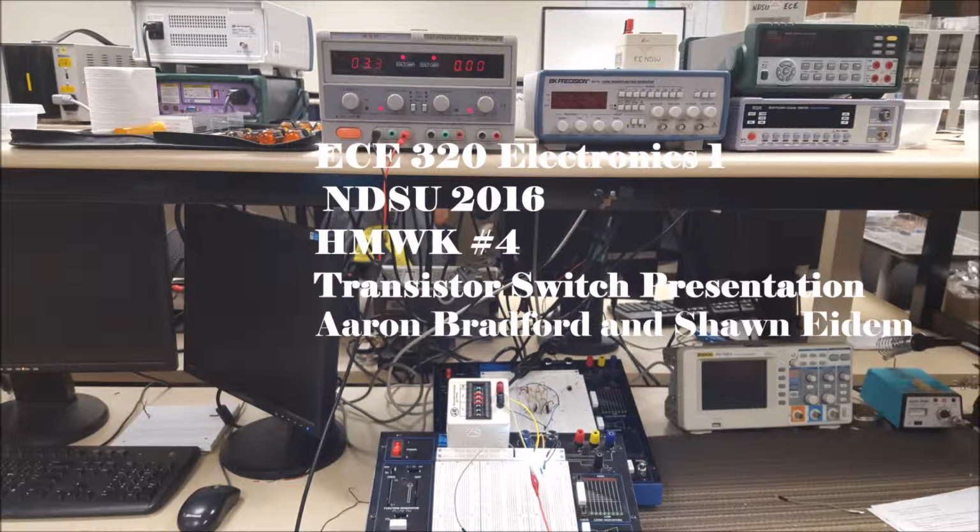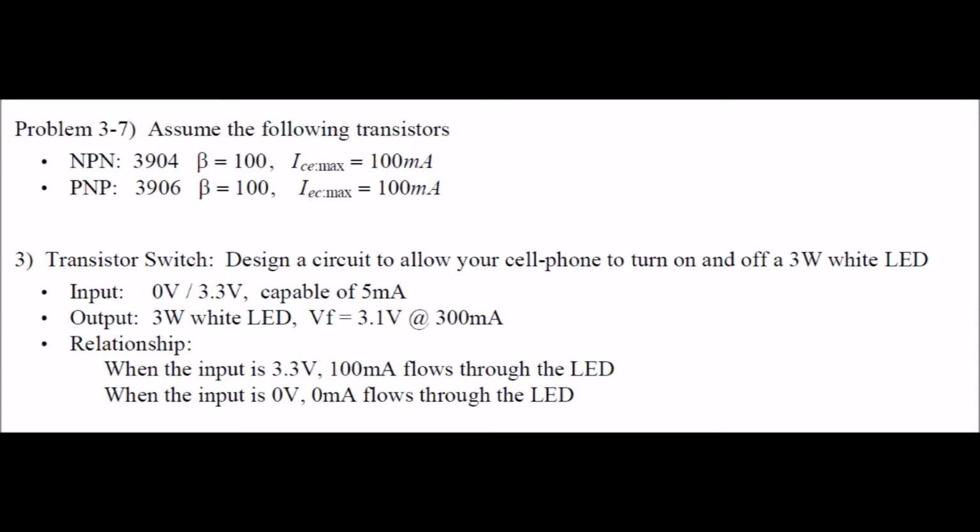We are students currently enrolled in NDSU and are bringing you all a presentation video from ECE 320, Electronics 1, on homework number 4. The demonstration takes place on the third portion of the assignment in which we are asked to design a transistor switch circuit. The circuit must be capable of using a cell phone to turn on a 3.1 volt at 300 milliamps white LED when plugged in and turn off the LED when unplugged.